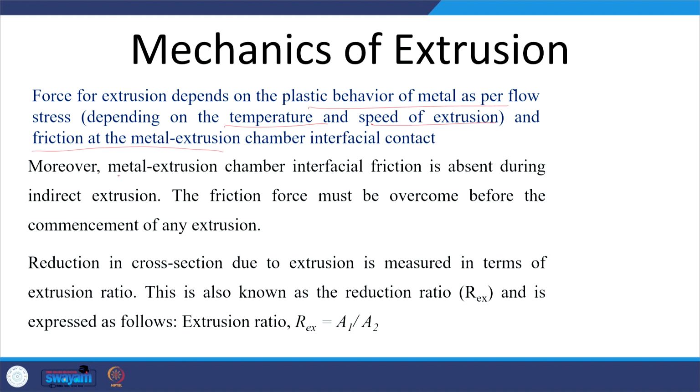Metal extrusion chamber interfacial friction is absent during indirect extrusion, and therefore it will require lesser force for the extrusion. The friction force must be overcome before commencement of any extrusion in the case of direct extrusion.